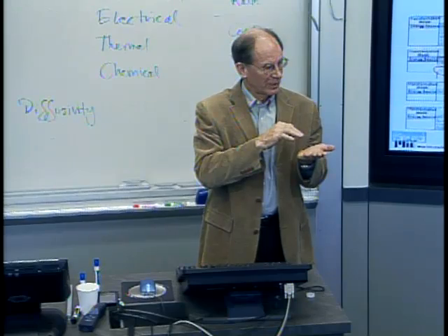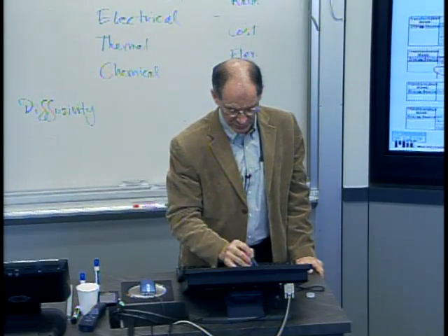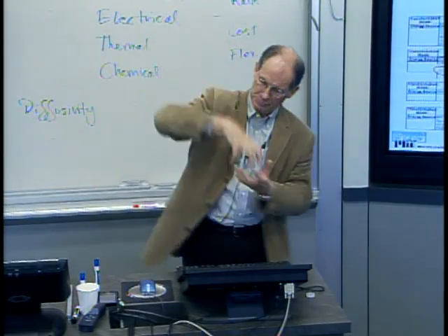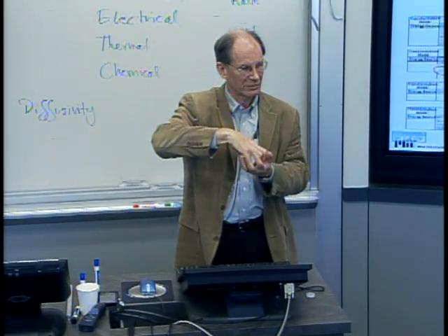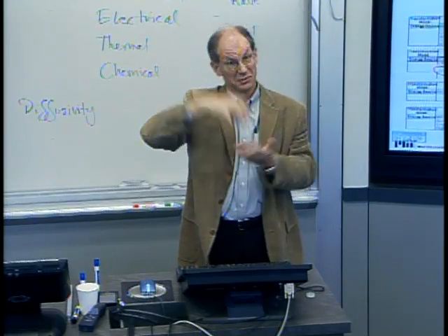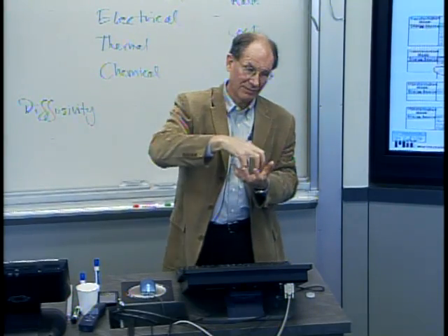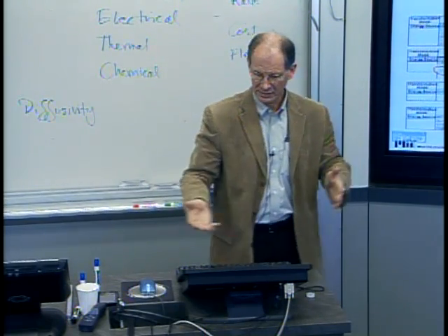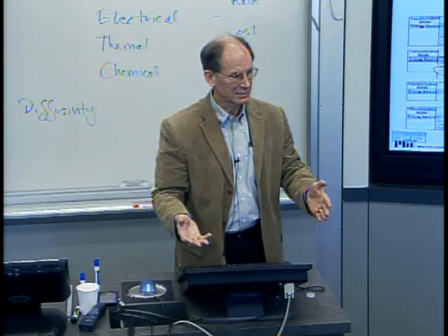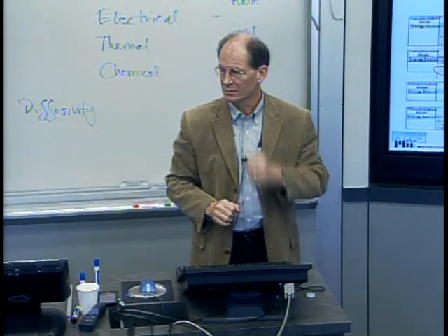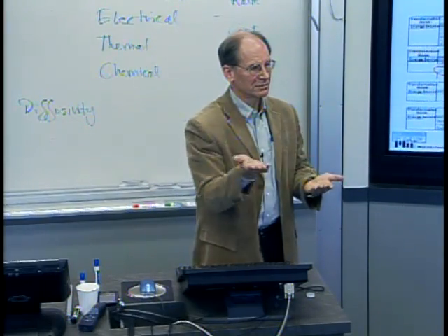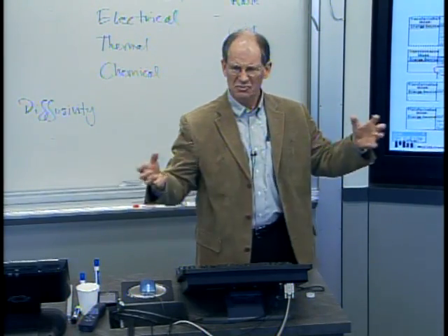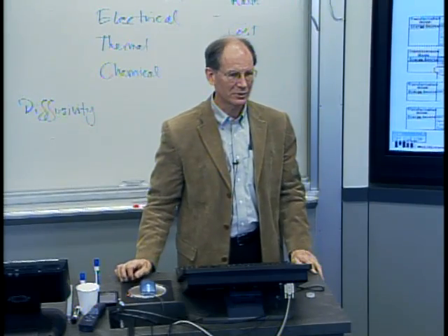Now it becomes a serial process. And think about the difference between these two processes. If I've got this big press that has to push this powder into a green compact, it's a big piece of equipment and I've got to have an expensive tool, whereas 3D printing is a desktop thing. There are desktop versions of it. All I have to do is type in a CAD file. It does a section file of it. It creates this thing, and I've got essentially equivalent parts. Not exactly equivalent, essentially equivalent parts.